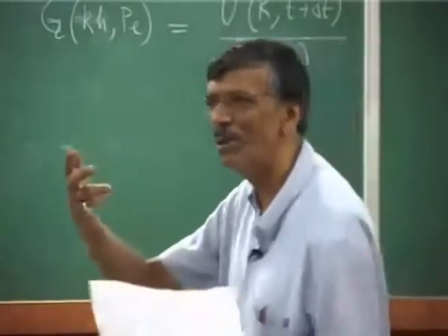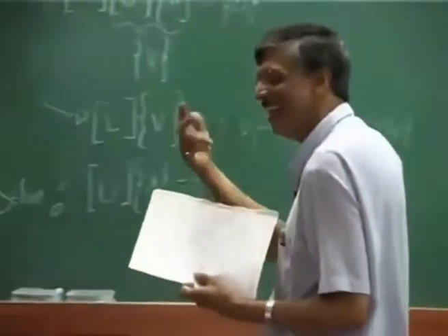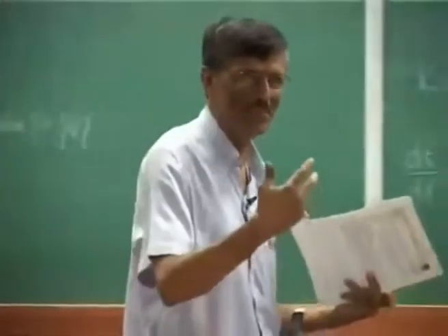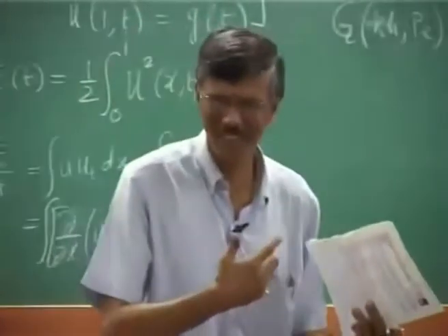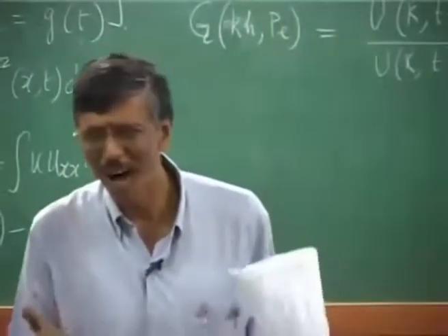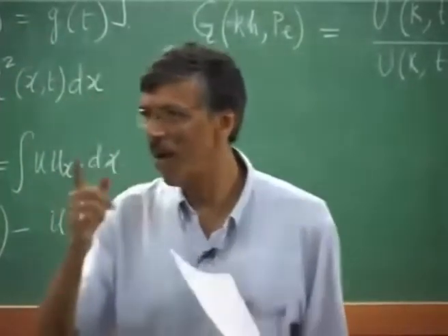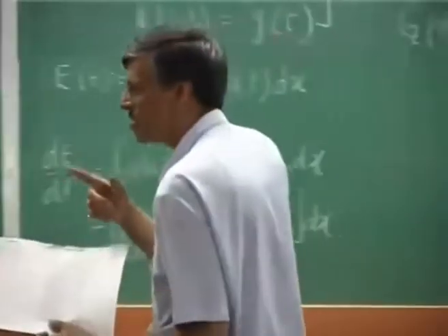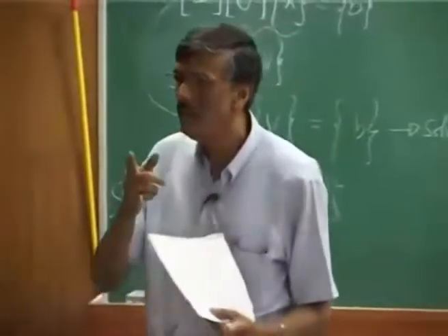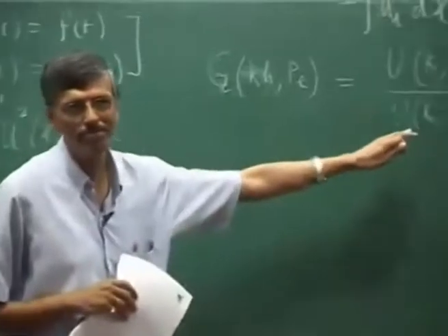The other guy may actually be doing more accurate calculations, but taking more time. And let me tell you, in my own personal professional life, I have been given all kinds of unwanted advice. People say, why are you doing so and so? It's tough, follow so and so. They have done it very quickly. But the point is, if you are interested in those transient solutions, if you are interested in accurate solutions, you do not want anything other than g equal to 1.